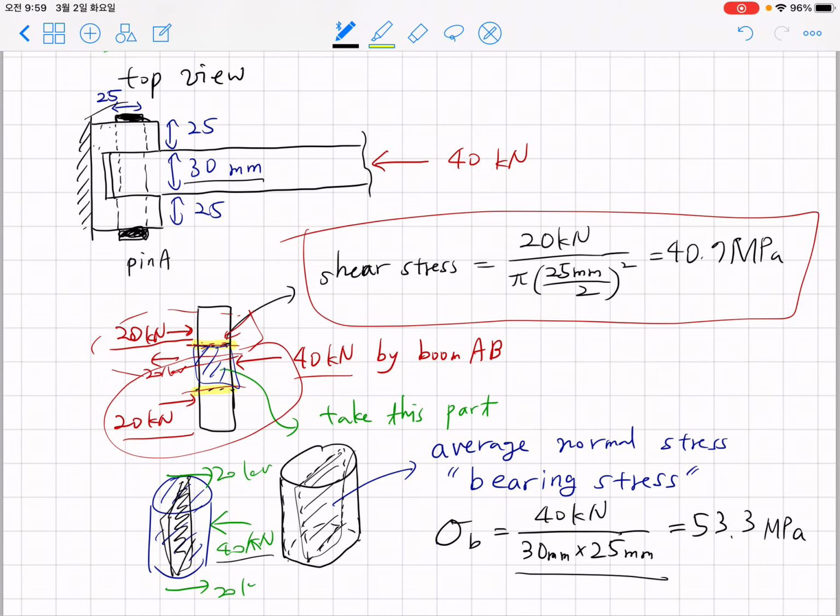When you construct real buildings and cars and real structures that are made out of bolt and nut joints and connections, if you think about a rigid body freshman physics problem, you only worry about the entire structure being in force equilibrium and torque equilibrium, and that's it. But in real life, you have to consider the safety of not only rod BC and rod AB, but also pin A shear stress, pin B shear stress, pin C shear stress, bearing stress, etc. So you can see that in realistic engineering, more complexity comes out.